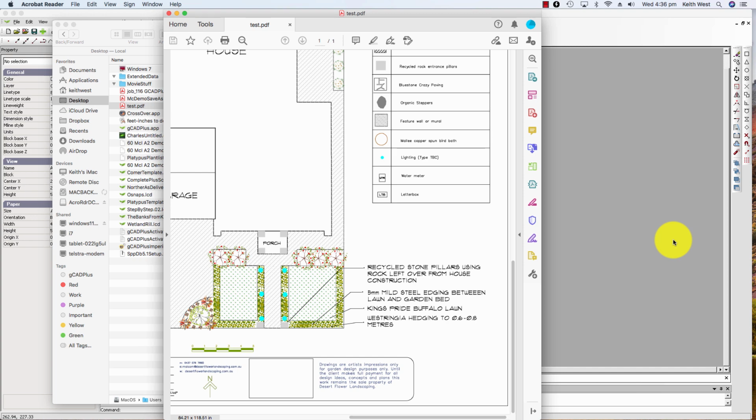So we can pretty confidently hand this over to a client, knowing that although in the title block information we will probably say not to scale, it includes a 5 meter scale bar. So with an appropriate ruler you could scale off, but we always put a rider on any drawing that dimensions that we apply in the drawing take precedence over any scaling off using a ruler.